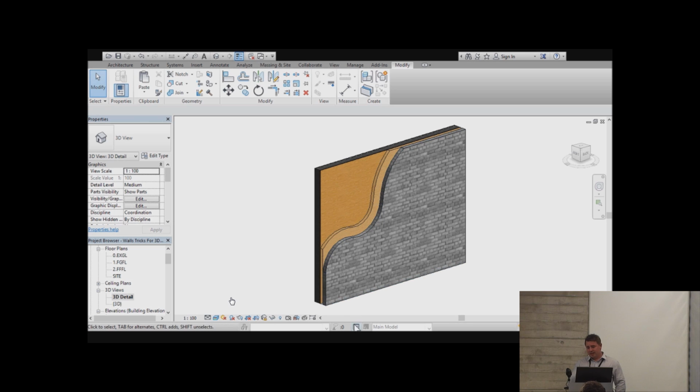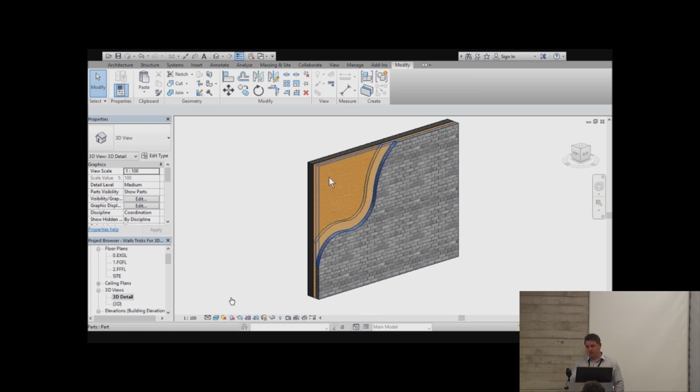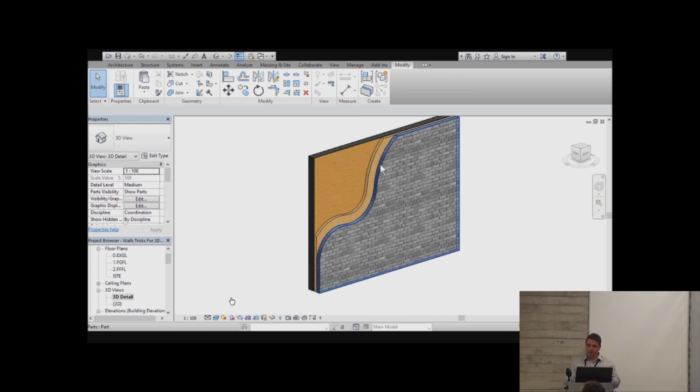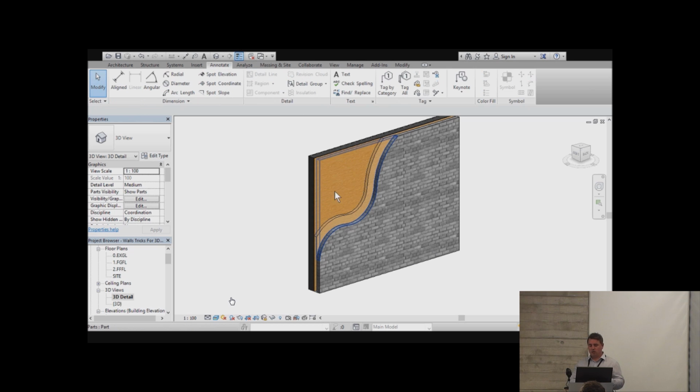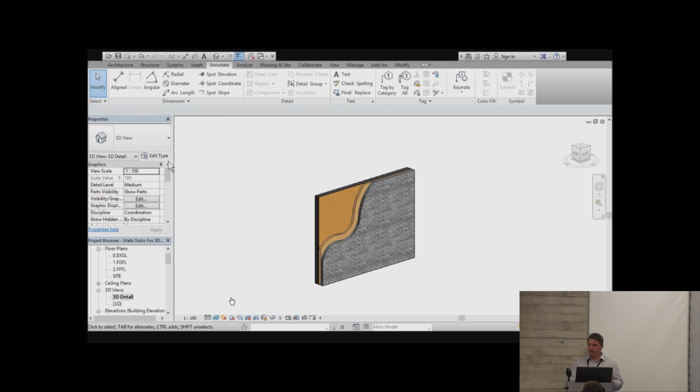So in this now, what I was showing briefly before is we've got this view, and I can fancy it up and sheet it up, whatever. But what I'm going to want to do is lock the view. So I've duplicated and locked this 3D view. When doing that, you're going to be able to tag in a 3D view, which you can't do without it being locked.